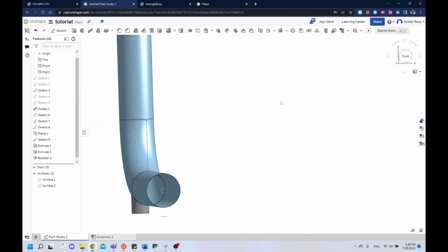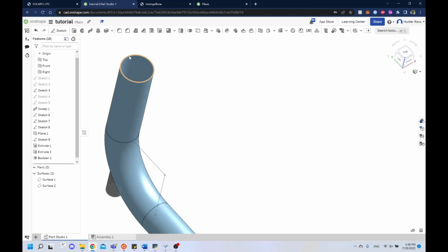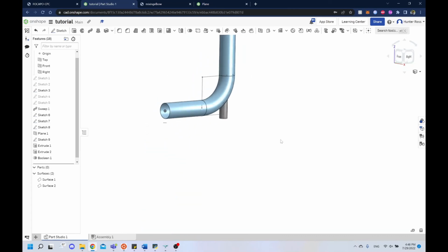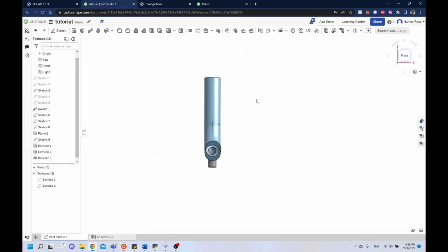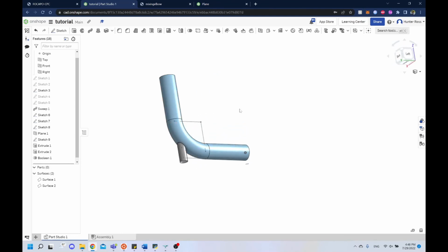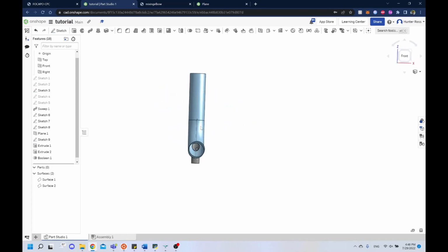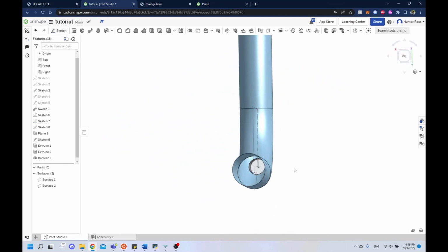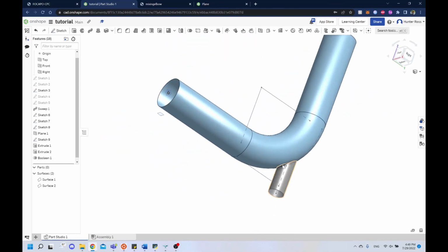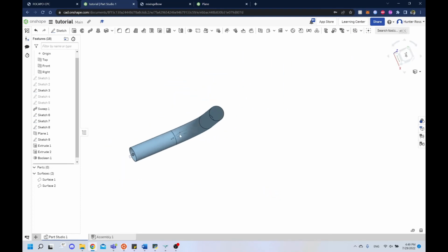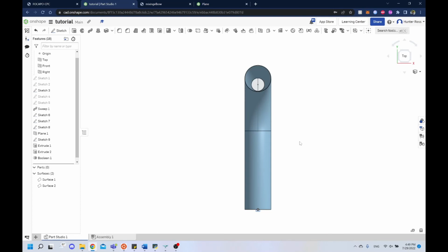one really odd thing is that you do need to make sure that this geometry is waterproof. So as of right now, if I were to dunk this section of pipe into, just submerge it into water, you'd see that water would flow through, right? It would go inside. When it comes to CFD in OpenFOAM, this cannot be the case. It has to be waterproof, and you'll understand why later, but I'll show you how to make it waterproof straight here from OnShape, so you can bring it directly into Salome and then move on to something called waterproofing, repairing, and meshing. So